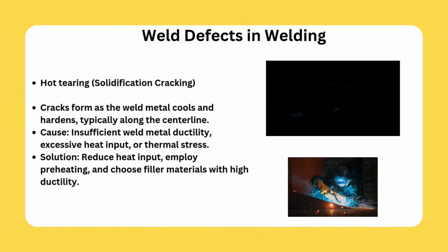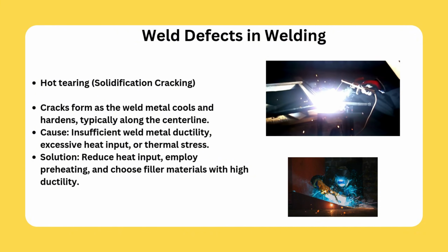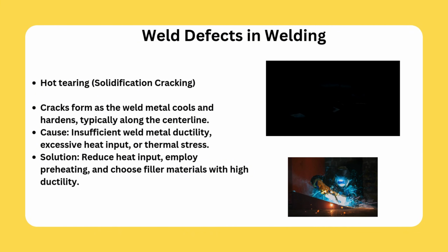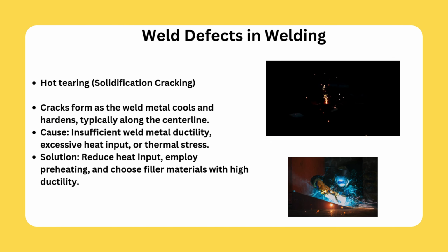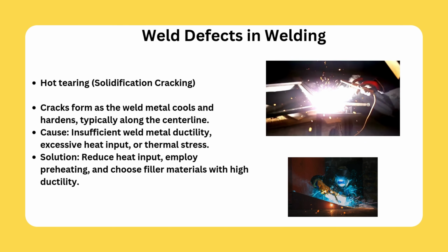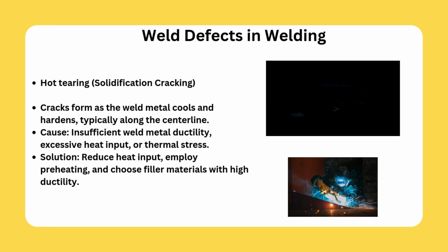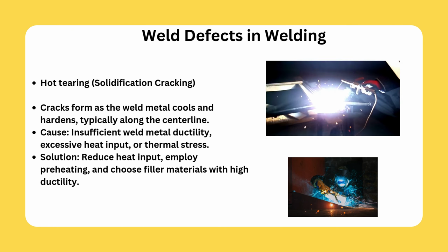Hot tearing, solidification cracking. Cracks form as the weld metal cools and hardens, typically along the center line. Cause: insufficient weld metal ductility, excessive heat input, or thermal stress. Solution: reduce heat input, employ preheating, and choose filler materials with high ductility.